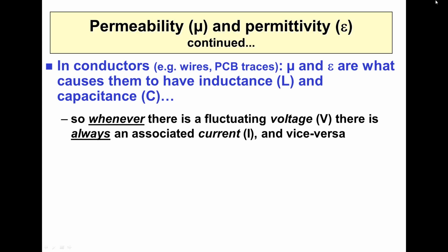Some digital circuit designers have been known to think that because their digital circuits have a low impedance output, but the digital gates have a high impedance input, maybe 10 megohms, therefore when they put a voltage on a trace, they just waggle the voltage around and there's no current in it because the load is so high. This isn't true. There's a significant capacitance associated with the gate, about 3 or 4 picofarads.